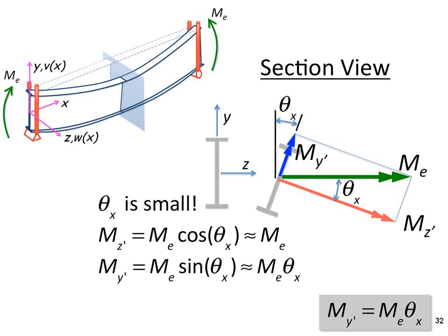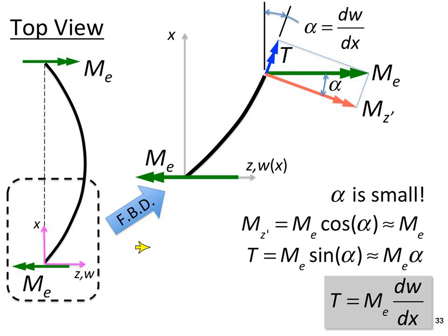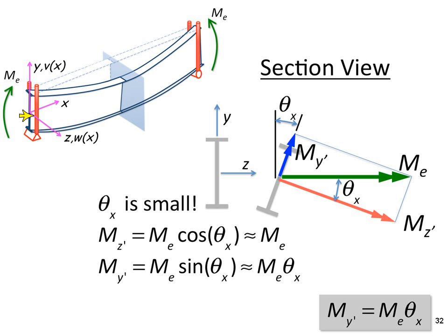So when we're talking about the torsion here, doesn't the torsional moment appear at the supports as well? And how is that taken into account in the derivation of the equations? Okay. Well, interestingly enough, as we move across the member, if you go to the next slide, you'll be able to see the torque from the top view. As we get closer and closer to the beginning here, I see what you're saying. The torque is pretty much absorbed right into the support. That's why it's so important that we have these supports that I'm showing here, because once this section buckles, there is a twist at the supports, and if those two posts on each end aren't there, the whole section is going to tip over and fall.